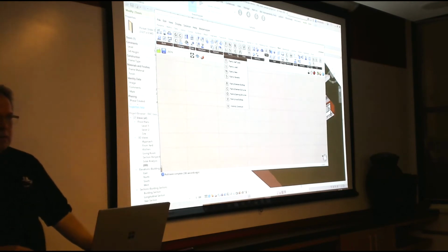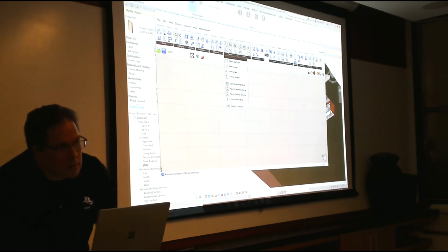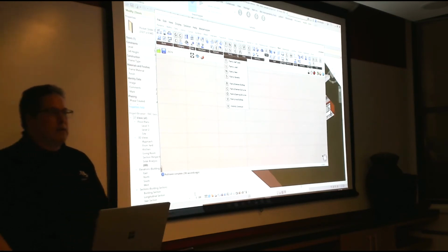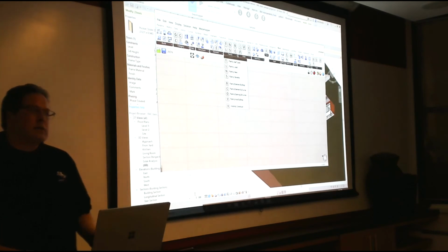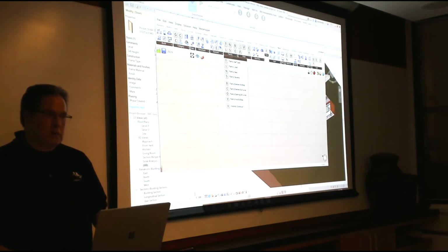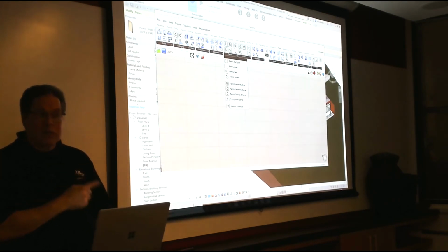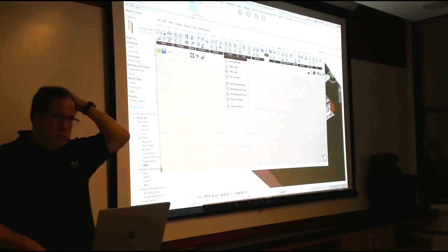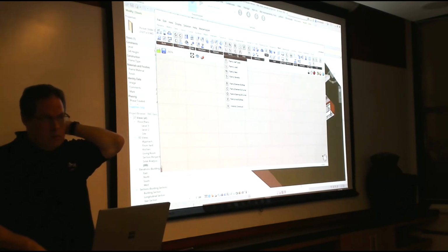I've also found that Revit is not very good at very small dimension objects. Anything lower than a millimeter edge, it will not take. What's nice about that is that you can use Rhino to find those edges if you want to and fix those. Or you push it in as a mesh and use the Rhino model. If you really need that thing to be less than a millimeter to fabricate, you better be using the Rhino geometry to fabricate. As far as we can tell, Revit uses an old ACIS kernel, so we're learning slowly but surely what it likes and doesn't like.